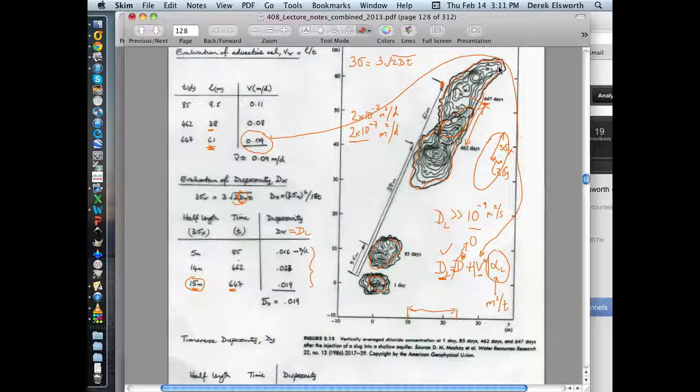And basically these concentrations were measured by just taking capillary tubes, so maybe a 1/10 of an inch diameter stainless steel tubes, physically pushing them into the ground, and then just sucking water out in them, and then measuring the concentration of the water that's pulled out of them. And so that's very easy to do if you kind of roughly know where you are.